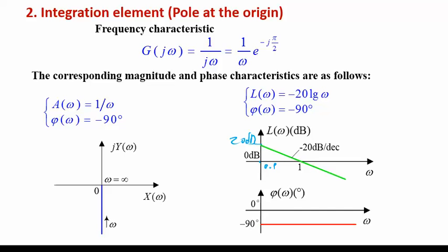So basically the slope is minus 20 per decade. Please leave this alone now. What if the frequency ratio is 10? 10 to power 1, so what would be minus 20? This is a line basically going over all frequency ratios, a line with a constant slope of minus 20, right?